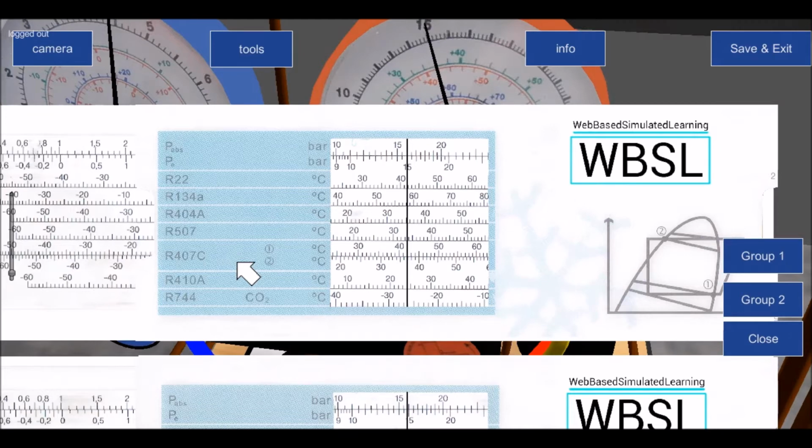Therefore, at a given stage, which is at the dew point temperature or the bubble point temperature, depending on whether it's in the evaporator or the condenser, all of the components reach 100% saturation, and that is the true evaporating temperature or the true condensing temperature. So in our case, we're looking at our bubble point temperature, because it's inside the condenser, which is the highest pressure on the pressure enthalpy chart, and the lowest pressure is the evaporator. Because we're looking at 15 bar, we are looking at our bubble point temperature, which is number 2.